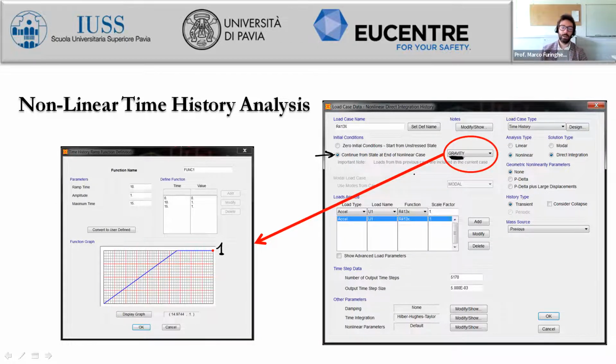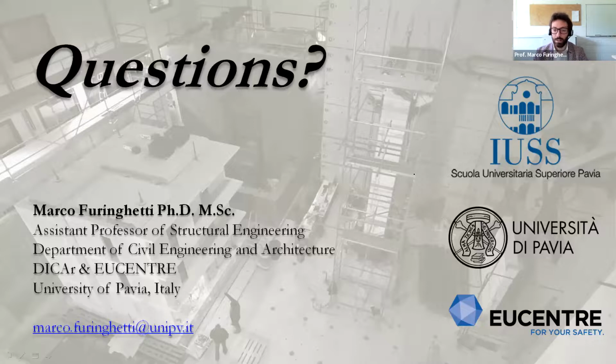So that all the links which represent the behavior of the curved surface sliders have the proper vertical load, and from that instant to the end of the earthquake simulation, there will also be the variation of the horizontal response with respect to the vertical force, stepwise applied to the links. So this is it for the modeling strategies within SAP 2000.